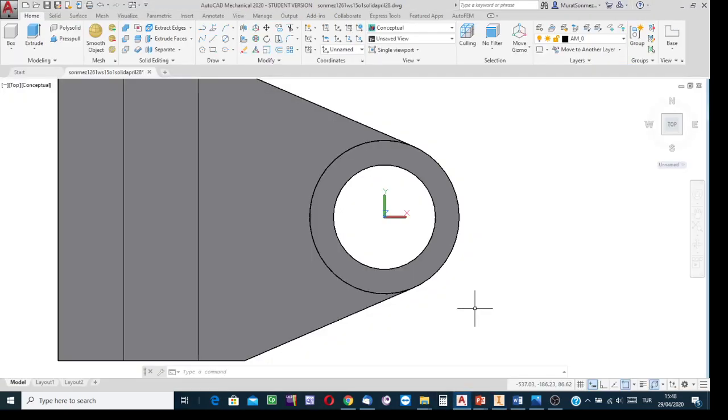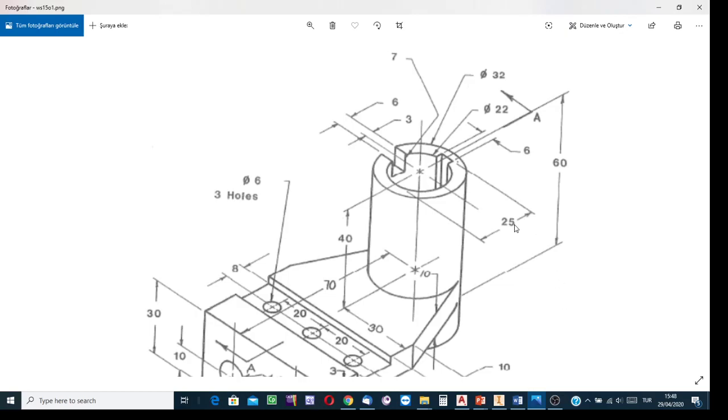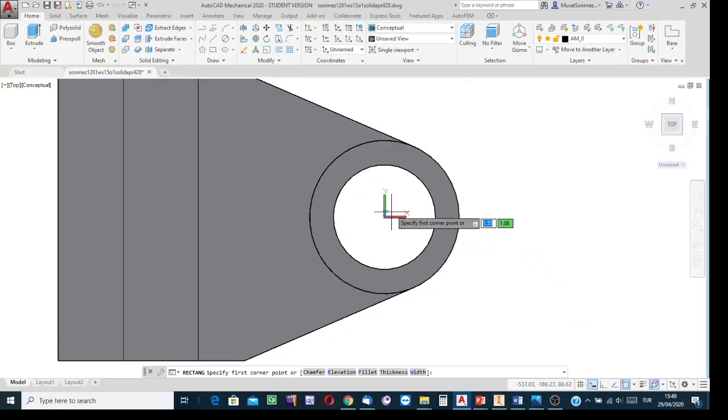See how such a rectangle can be created. Start the rectangle creation process, and for the upper right corner, write the coordinates. The abscissa value I already calculated: 25 minus 11, equal to 14. Abscissa is 14. Ordinate is, see the origin, the origin is over there.